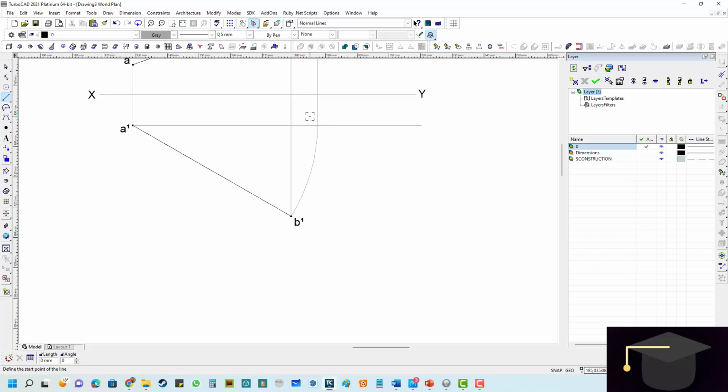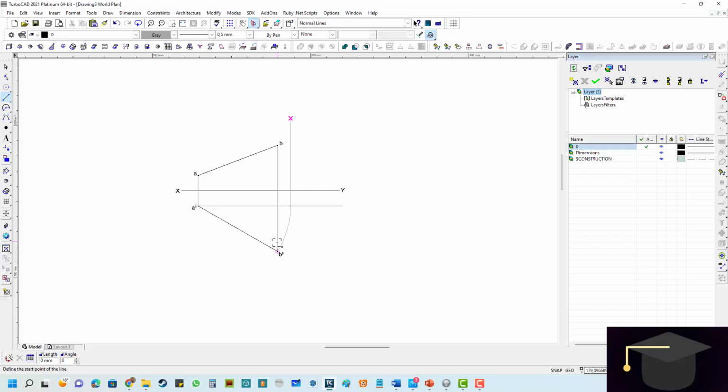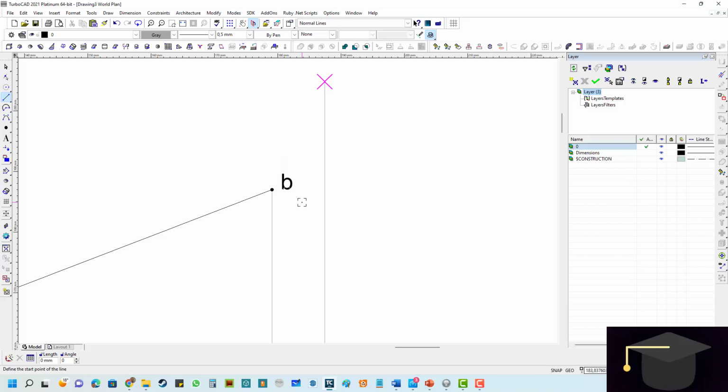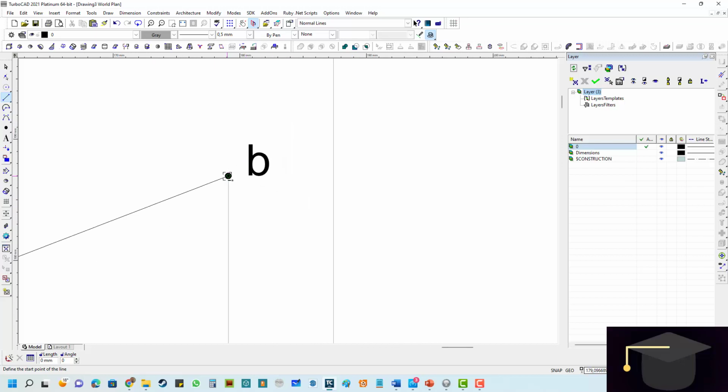So now where we have taken B1 and swung that around, we now have to, in our front view, take that point that we have been using and manipulating, and from that point B on the front view, hold down the shift by clicking on the center of that dot, drag out the construction line and place it perfectly parallel to the XY as well.